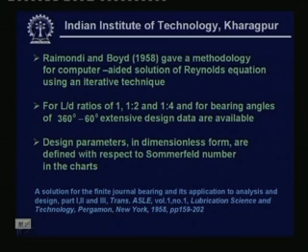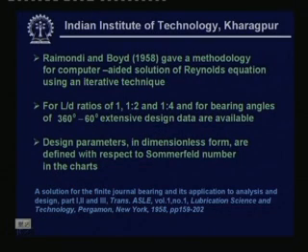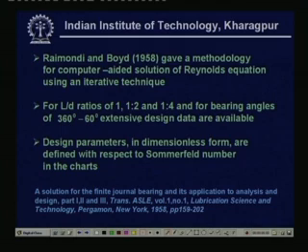Some iterative techniques have been used, and this solution depends on the type of bearing, means for different kinds of journal bearings the solution exists. You can see for L by D ratios of 1, 1.2, 1.4, and for bearing angles 360 to 60 degrees.